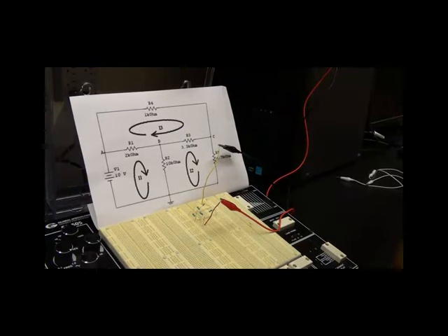The common problem that we normally see from the students in the lab is that they connect the resistors or any components in the same hole. Two pins are in the same hole, which are connected. After you implement the circuit, just visually inspect your circuit and make sure there is no component. Again, the rule is that there is no component that has two pins in the same connected column or the same connected row. So always, if you follow that rule, you'll be okay, and your circuit and your troubleshooting would be much easier.